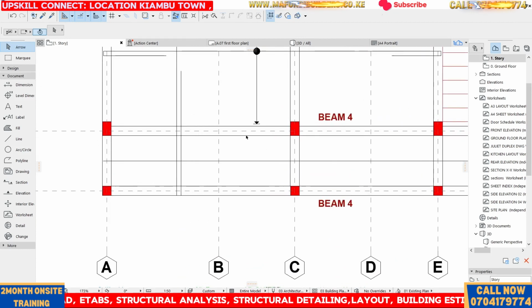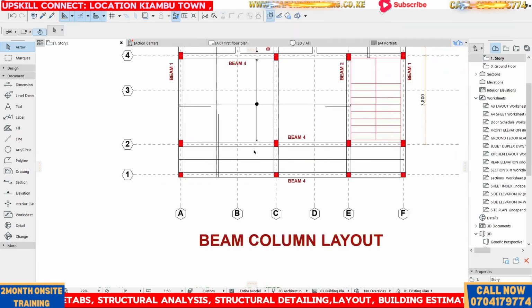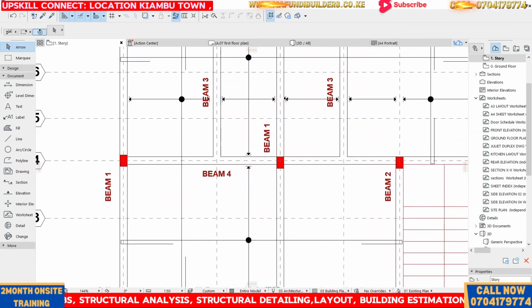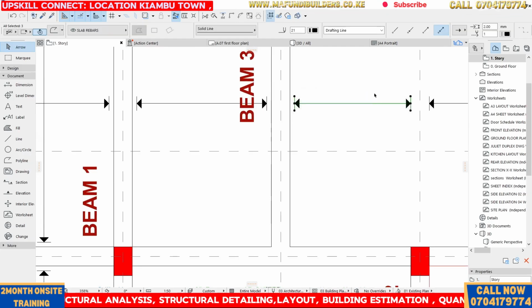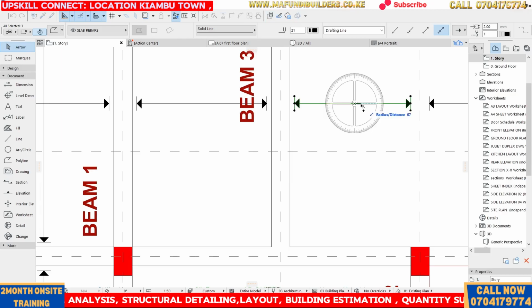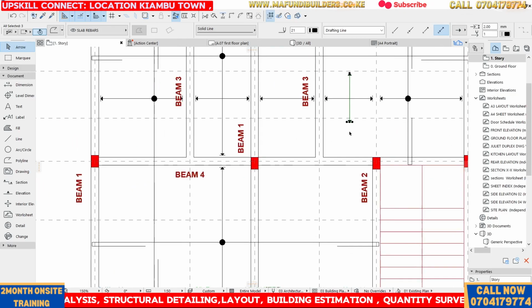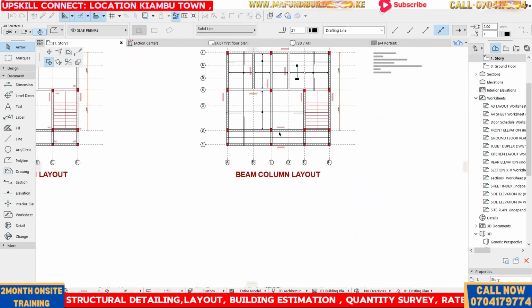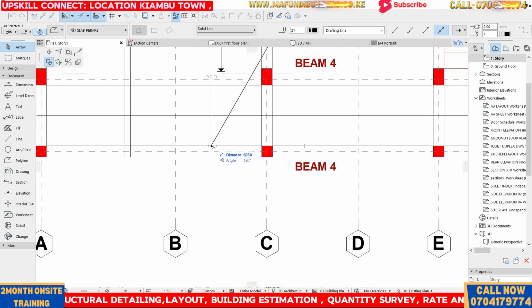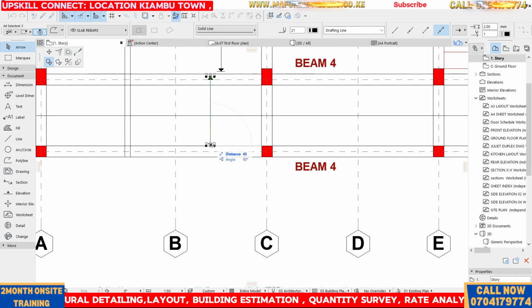Now if you want to show the distribution for this bar again, you can probably come and pick, like this one, because it's similar. Control Shift E for rotate a copy, like that, and bring it here. And you can move it by 50.